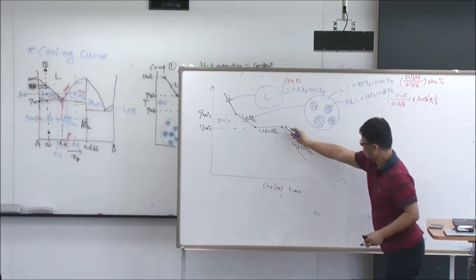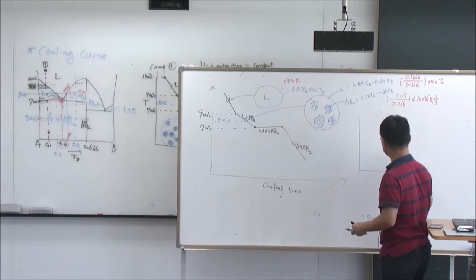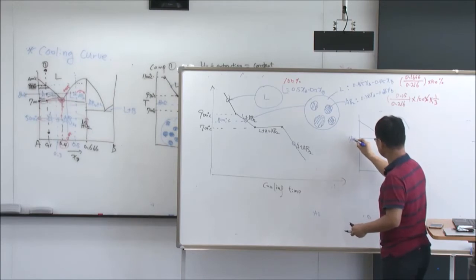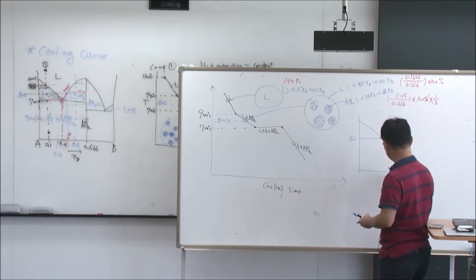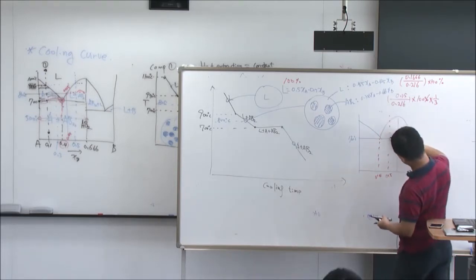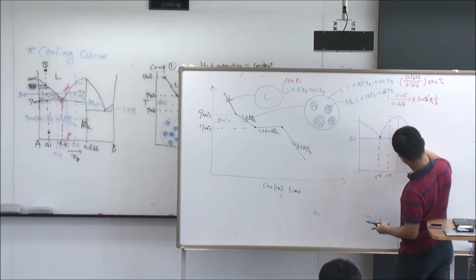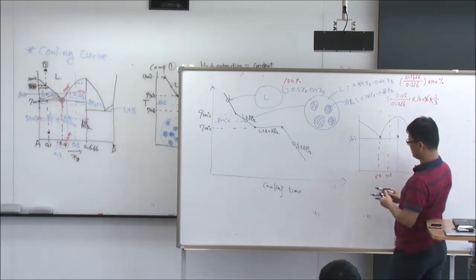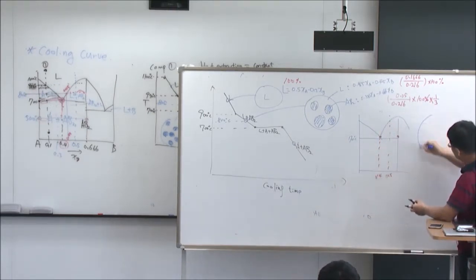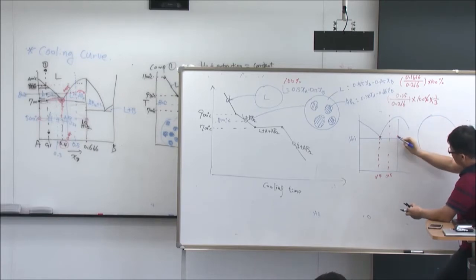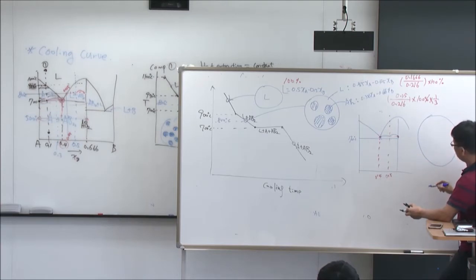So, as I mentioned, during this eutectic reaction, if you look at it in that diagram again, this is 700 degrees Celsius, and we are talking about this composition. So, just above the eutectic temperature, I have this liquid phase and this solid phase, yeah? So, the microstructure AB2 is originally this amount of liquid phase, this amount of the AB2 phase.